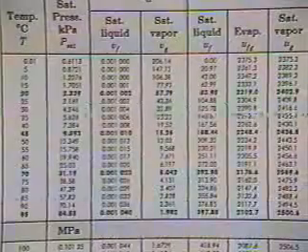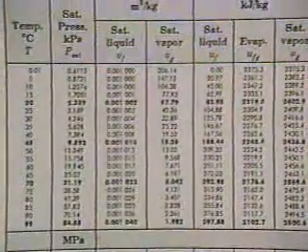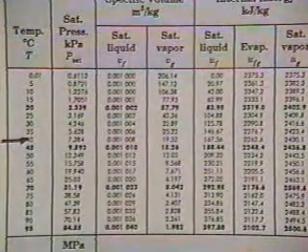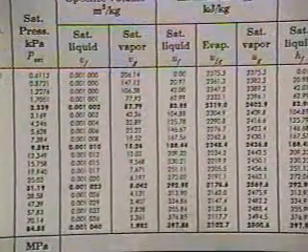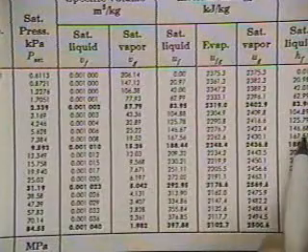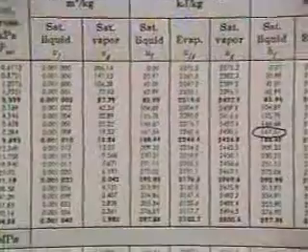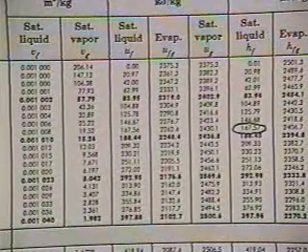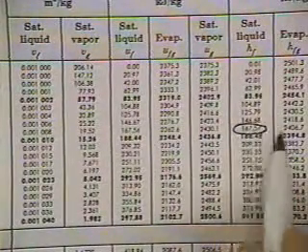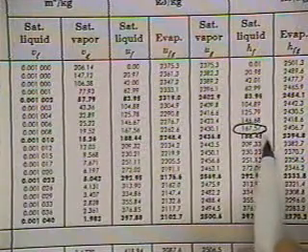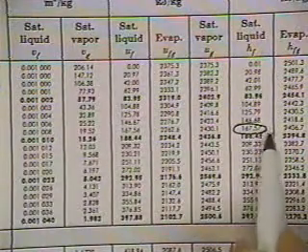In this particular case, we have 40 degrees C, and so what we will do is come down to 40 degrees C in the table and go over to the enthalpy at 40 degrees C, which is 167.57. And so the state 1 would be found at 40 degrees C, saturated liquid condition.